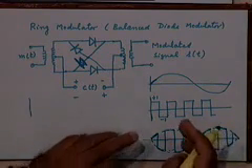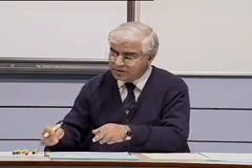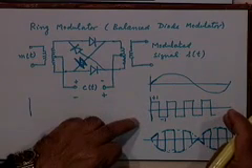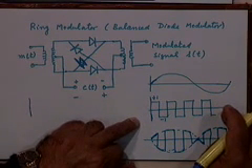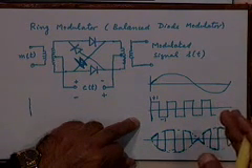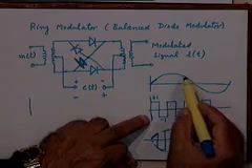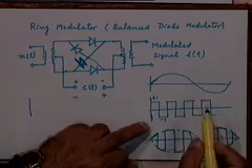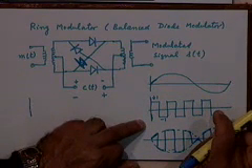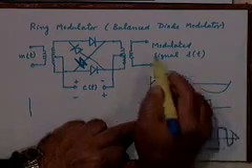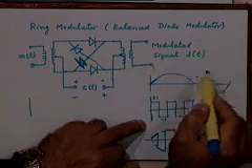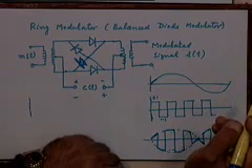So what should I do? If you remember, the basic theory remains the same. M of t is multiplied with the square wave. Square wave contains this fundamental component and its harmonics, odd harmonics. So we want only the component which is a product of this M of t with the first harmonic of this, right. So what should we do? Simply pass this through a band pass filter tuned to the carrier frequency Fc.